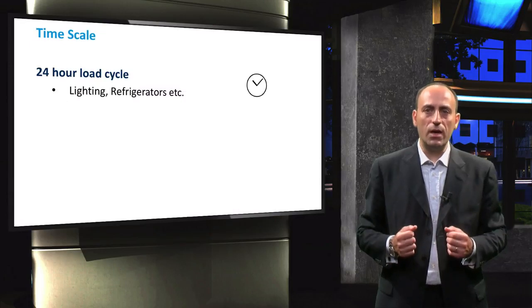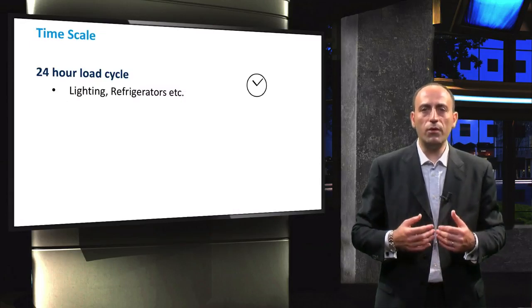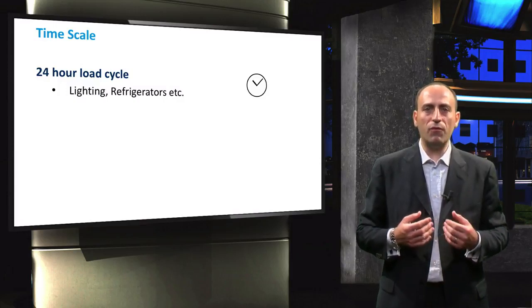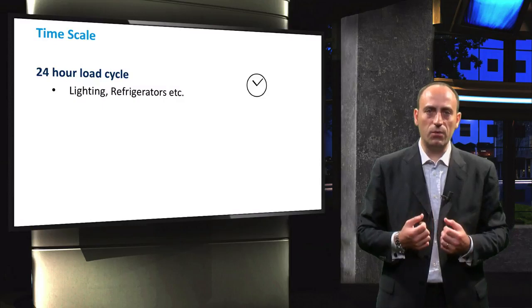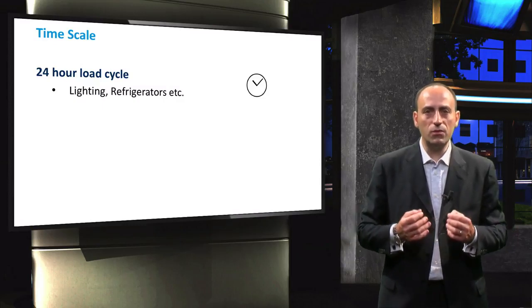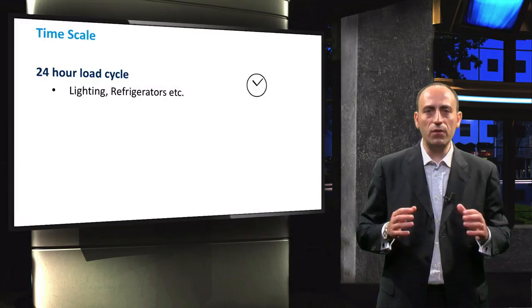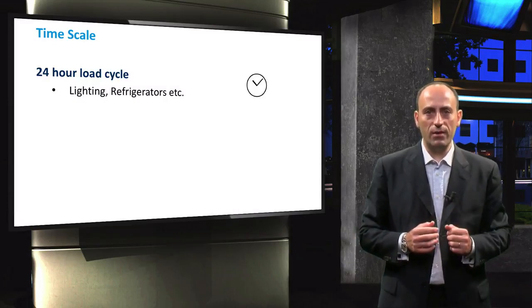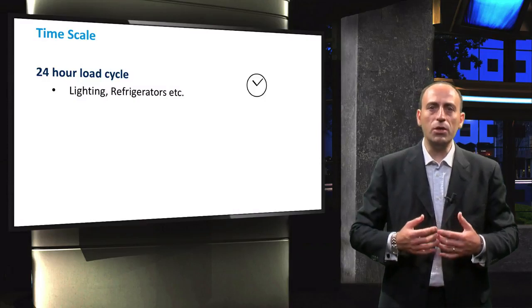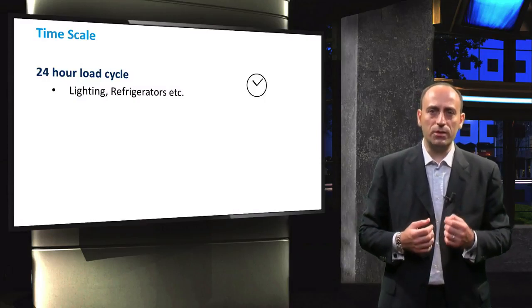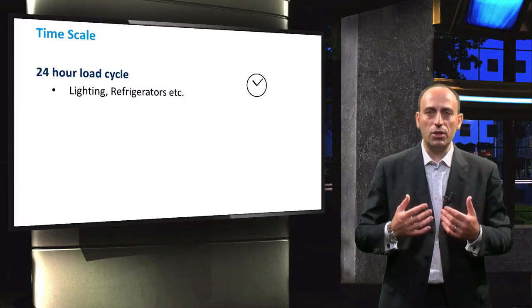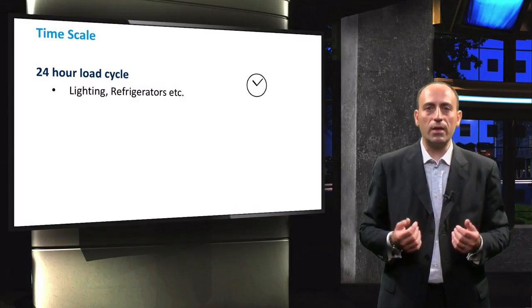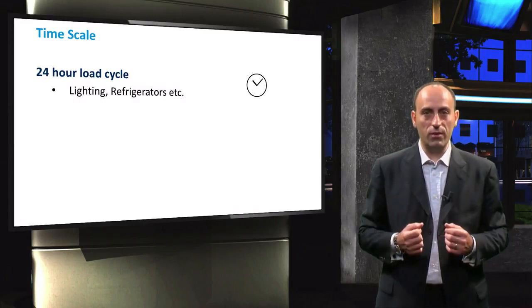In PV system design, load profile analysis will often depend on the available resources. Analyzing a load profile can be performed with increasing complexity and accuracy. The simplest model is to determine the load profile over a 24-hour load cycle and assume the load profile is the same every day. This can be achieved by monitoring the electricity consumption for an arbitrary day. However, such analysis might not include all the available loads, as it might not take into account the loads that are not operated every day.